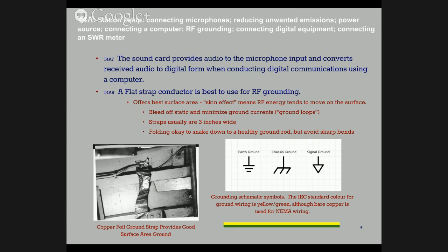Mostly now, the same function of a TNC can be done with a computer sound card. Modem comes from modulator-demodulator, and since we're modulating at audio frequencies, it's definitely something a computer sound card can handle.